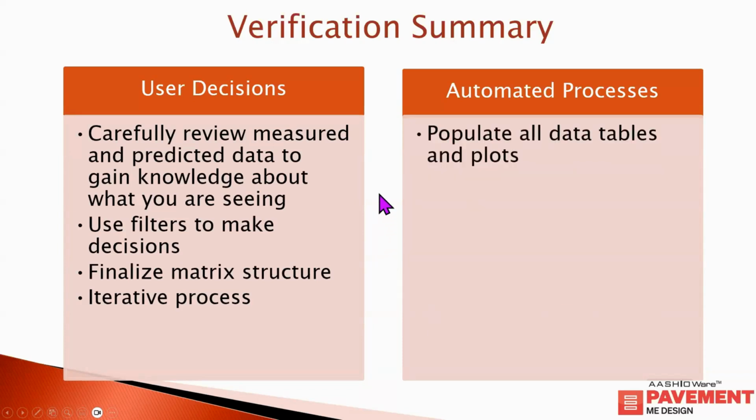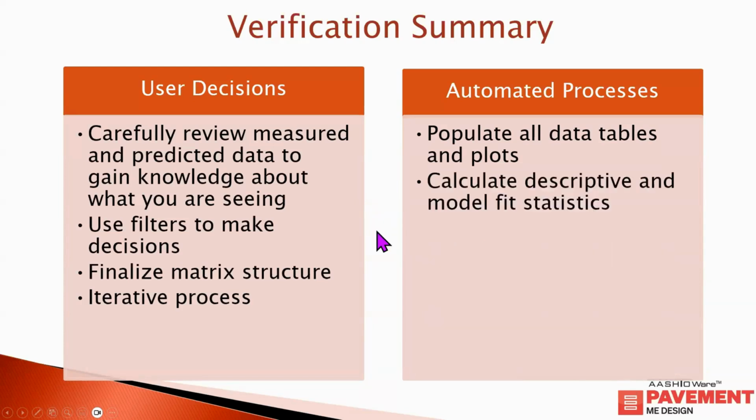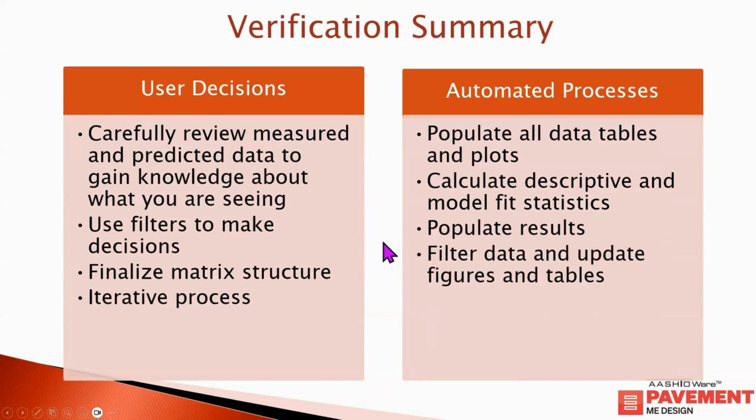And what the CAD is doing for you, it's doing, again, the heavy lifting. It's populating all the data tables, plots, calculating the ANOVA statistics, and populating those results for you to look at. And then if you filter the data, it updates all the figures and tables. So it's doing all the analysis for you.